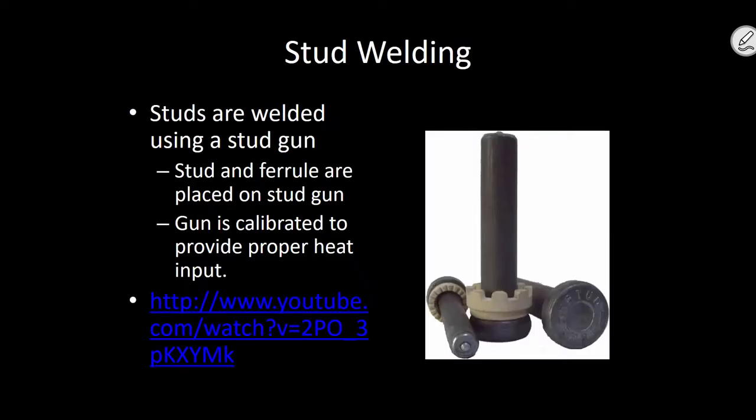Now, I do want to talk a little bit about the stud installation process, just so you have an idea of what's going on. So this is an image of a typical shear stud. Here is the actual stud, and then this ceramic little cap on the end of it is what's called a ferrule. During installation, that actually contains the heat input during a stud installation.